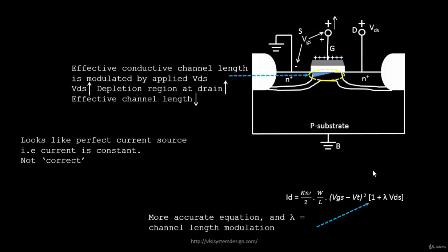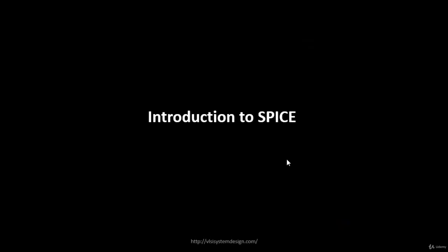So we came up with a threshold equation in the beginning, then the drain current equation for the MOSFET in the linear region, and now we have the drain current equation for this MOSFET in the saturation region. We will use these three different models and try to do this SPICE simulation. This is the right time to introduce you to SPICE.